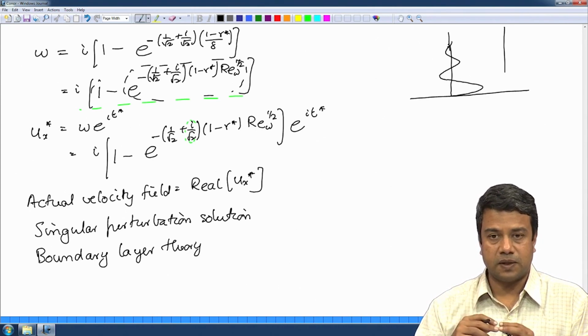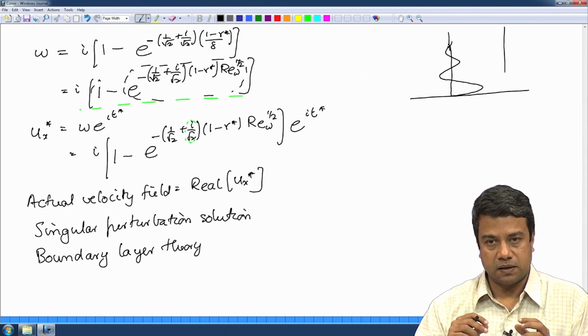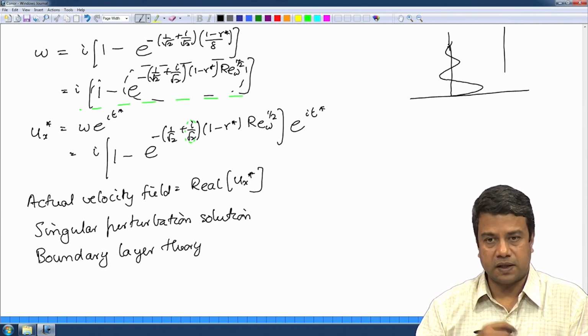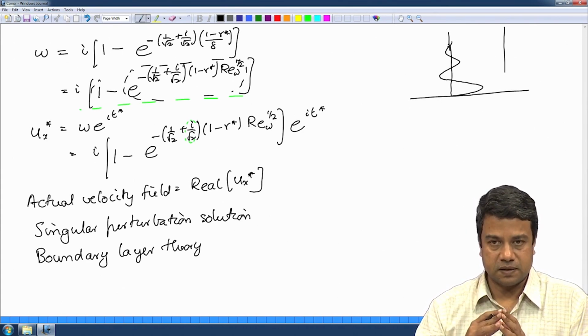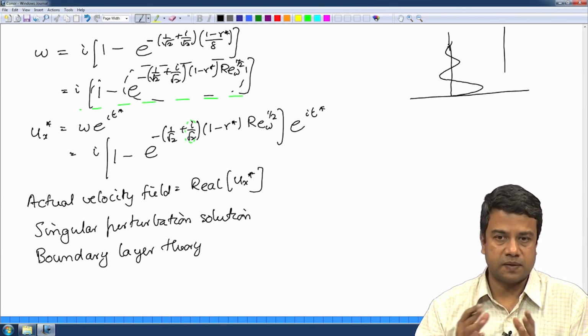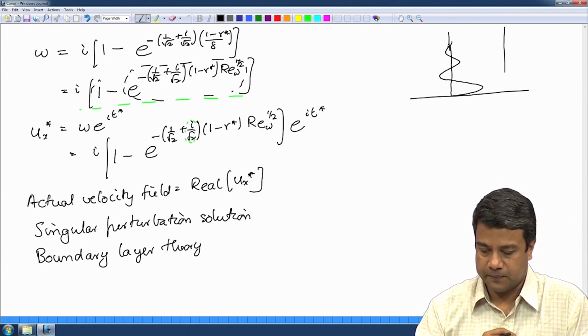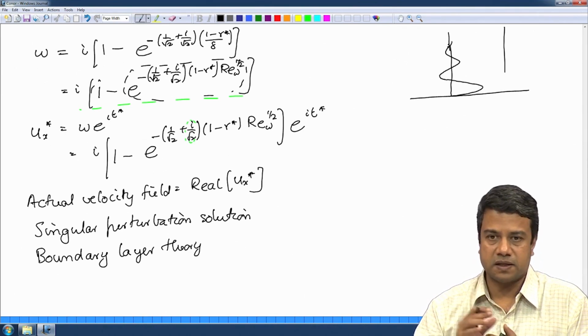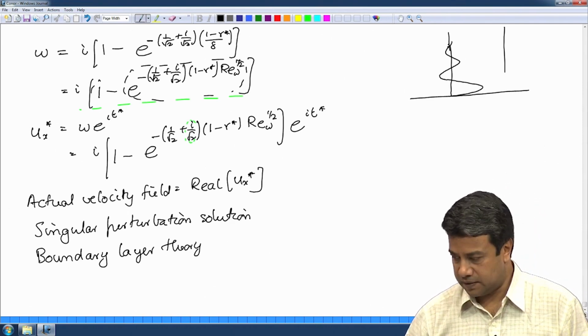But once I scale it that way, within this region the inertial and viscous effects are of equal magnitude, and therefore I can solve the boundary conditions and from that calculate the flux at the surface, by taking the derivatives of the temperature field or the concentration field. So this serves as an illustration of what I have been emphasizing throughout, that when inertial effects or convective effects are dominant, diffusive effects still have to be incorporated within a thin region near the surface.